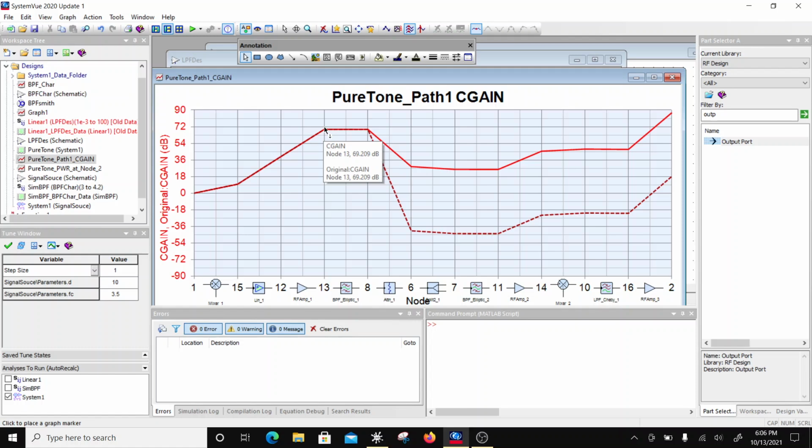So the gain was 30, right? So 39.6, it should be 69.6, so it is a 0.4 dB compressed here. So the PA is 0.4 dB compressed here when it is putting out 27 dBm, right, in two tones. And then this one basically is showing you gain. Yeah, so I'm putting high power.